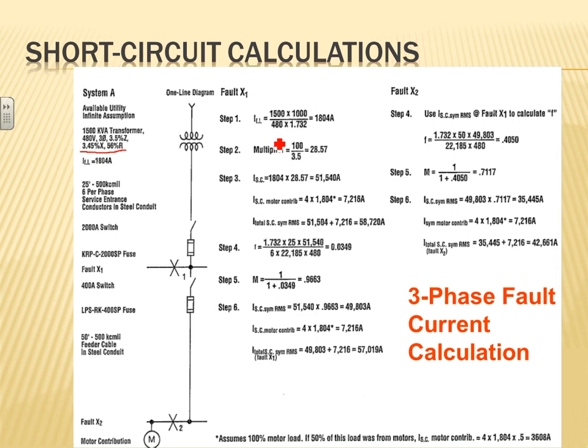So based on the impedance, what we do is first, for the transformer, like you guys know, find the full load current of the transformer: take the kVA of that particular transformer divided by the voltage and the 1.73 component for the 3-phase. Then you divide that value by the impedance of the transformer. That will get you the multiplier, and then you multiply the multiplier by the full load current, and that will give you the available short circuit current right at the terminals of that transformer.